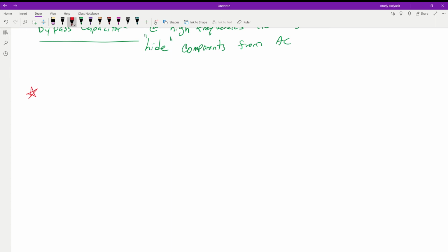And especially with the calculations you guys are going to be doing, because we can't accurately measure that inductor, you could build your test circuit with a known frequency and known resistance values, and go through and see when your voltages line up and things like that.